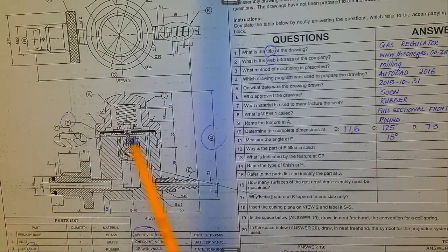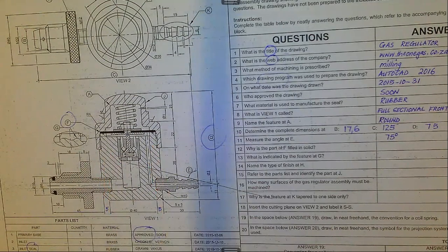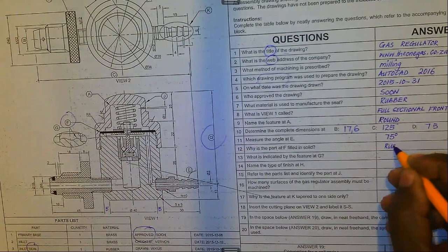So if you see black like that on a pump, on a machine, in a mechanical drawing, you know that it is representing rubber. Like I said, you can also have that thinnish material, representing a thin material which cannot be hatched by normal hatching processes, or which we cannot show the actual size. Then we represent it by a thin line. But in this case, that is a seal, which is an inlet seal. That's a rubber. So we write here, that's a rubber.